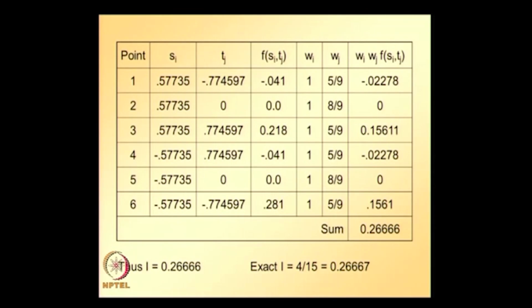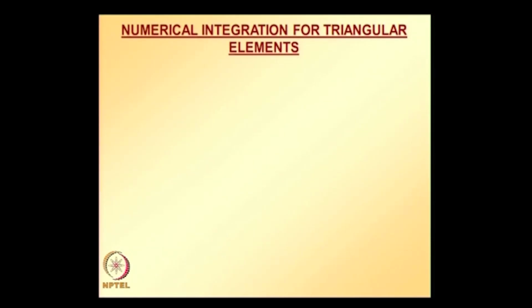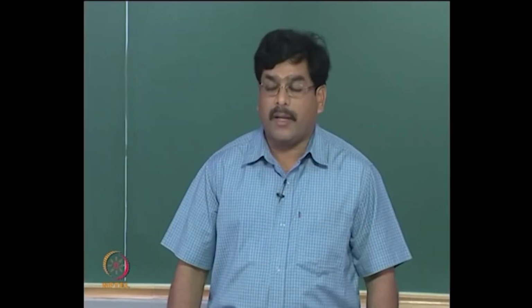So this is about applying Gauss-Legendre rules for evaluating integrals over a rectangular area. Now let us look at integration for triangular elements. This integration for rectangular elements and integration for triangular elements, these details are very important for finite element equation assembly or finite element equation evaluation.